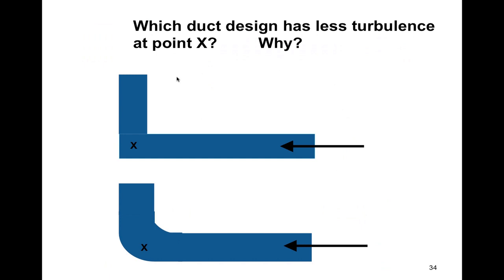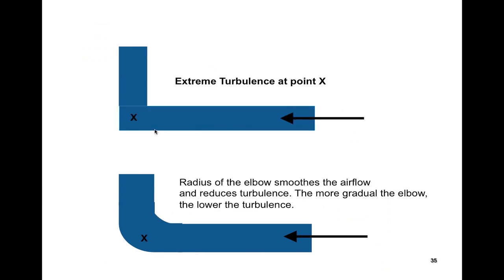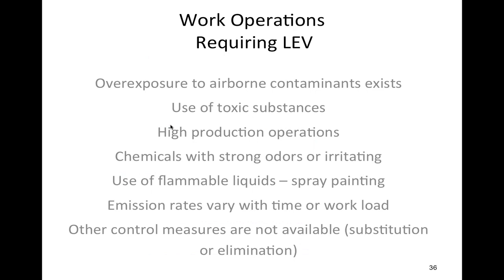Okay, in this situation, where would you think there's more turbulence and more loss of suction pressure? It's going to be at this curved portion, at the squared off portion, right? You've got turns, transitions. You want to make them as smooth a transition as possible.